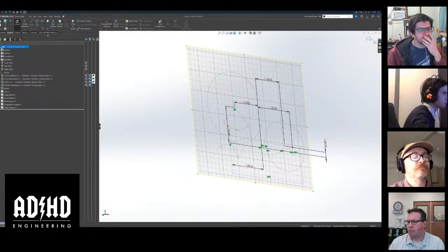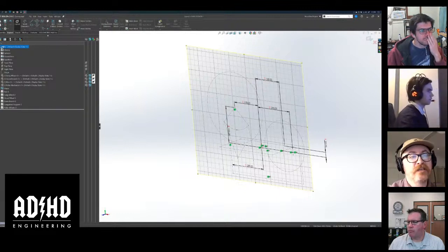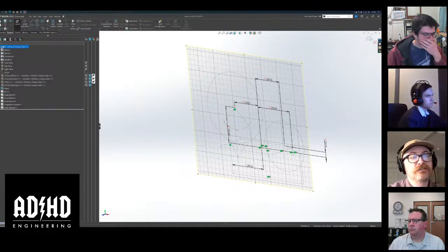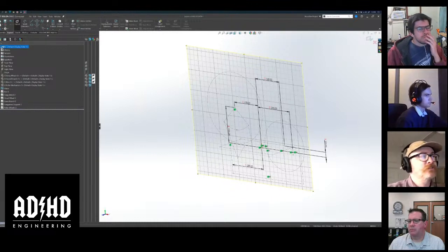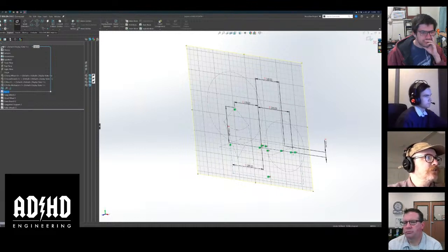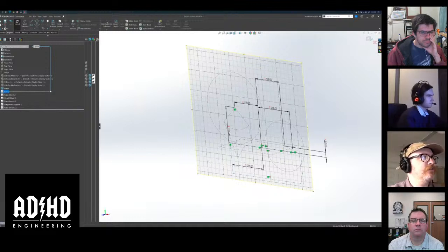Yeah, so the blocks become your source geometry, not that plane. Because the blocks are on that plane, you can make a plane in your part that is coincident to the points on the block. So then that plane lives with the part, but it goes back to the absolute starting geometry in this layout sketch. So anyway, the first one I laid out was the box. And if you notice in the feature tree, I have enabled it so that you can see where this entity finds its geometry. In this case, it is in the layout.